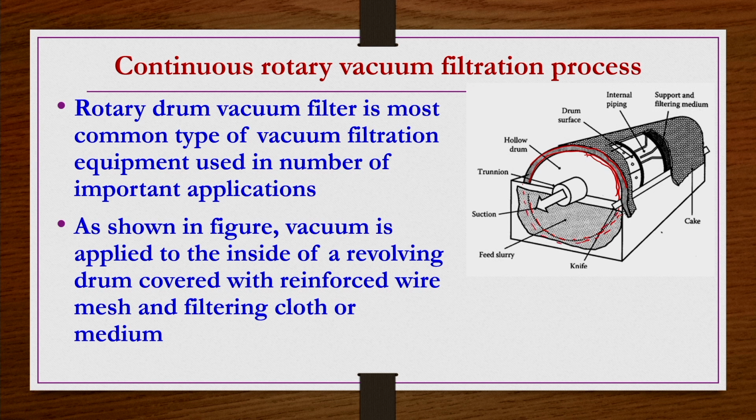Something like this. Now, this drum is covered with a kind of filter medium or filter cloth. So, this drum surface also has a porous structure, because of the openings in the drum, the liquid can pass through and only the solids are deposited.